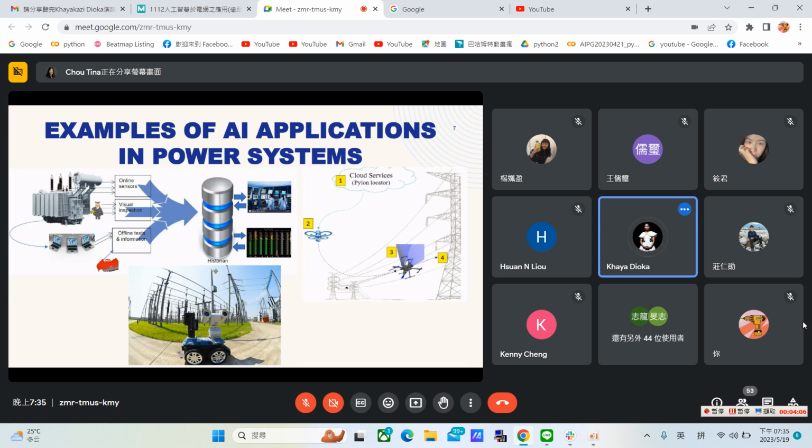So this is really very few of the examples that I had picked up to just indicate how you can apply AI in power systems, and some of these actually have already been implemented. Others are on the rollout. Like on transformers, we are rolling out what you call an integrated condition monitoring system, because currently all our condition monitoring systems are either monitoring bushing, checking the PD, or doing the DGA system, which is mainly our condition monitoring system that's in service.